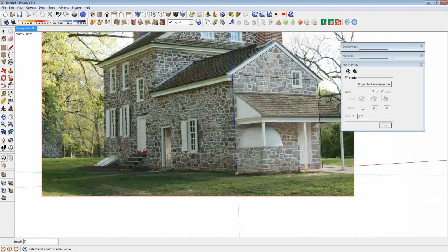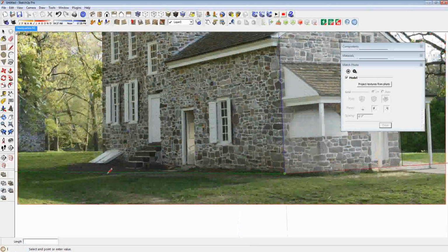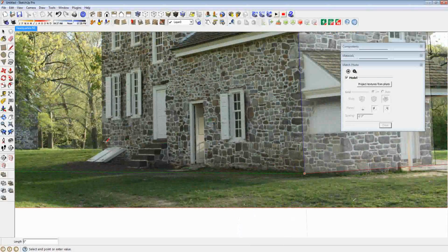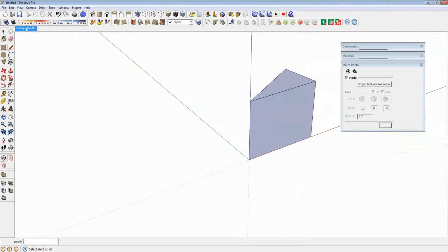And it understands what direction I'm going because, again, I set all this up in the very beginning off that photo. Get that out there. Good. Oop. And again, if I accidentally orbit, just come back to that view. That flattens it out again.